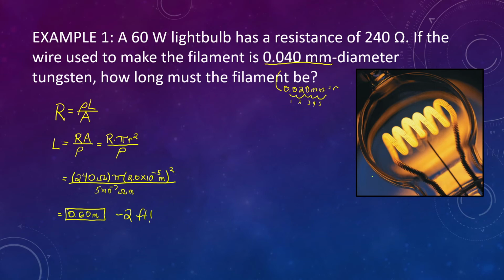So inside of the light bulb over here, that filament is coiled around twice. Notice that it's coiled around in a small little coil, and then that coil itself is spun around in a coil in the middle. Well, it's like that so we can fit such a long wire inside, a long filament. Because remember, the longer the wire is, the more resistance there is.